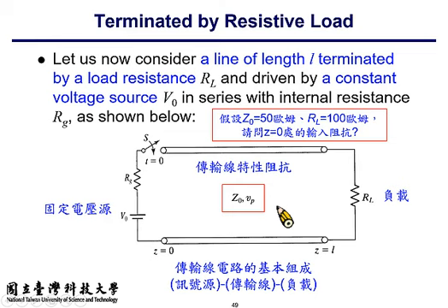And again, when this signal reaches the right-hand side, you have impedance mismatch, so you will have another signal labeled as V minus plus minus. Right? So the labeling rule is quite straightforward. What happens next? You have another signal, V minus plus minus plus. Right? So on and so forth. Okay. So this thing will continue.